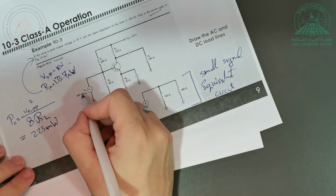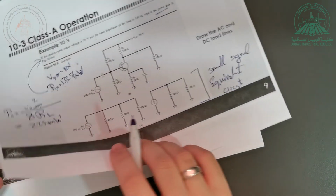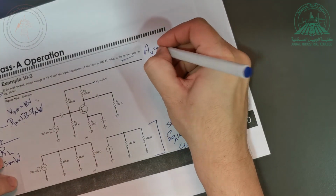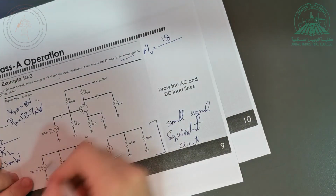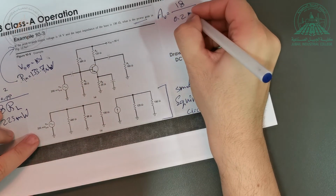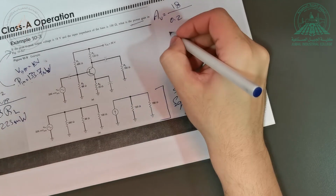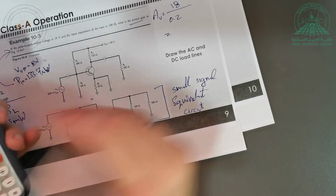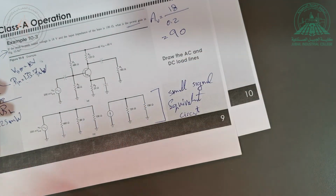And Pn here is equal to how much? The power supplied here, Pn is given here. So if you want to talk about AV, the voltage gain, how much is the voltage gain? From 200 millivolt originally, 0.2 peak to peak, it became 18 V out over Vn. So how much is that? 18 multiplied by 5, 90. So 90 times. It means the voltage was amplified by 90 times.